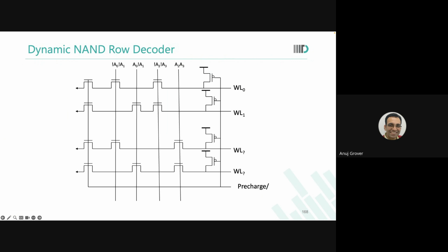You have to really play with the memory, play with these design techniques, and then you will be able to arrive at what is my final PPA. In memory design, do not consider anything as sacrosanct, except that area is diamond. Area is diamond, area is diamond. This is the baseline. Everything else you do, you have to evaluate.